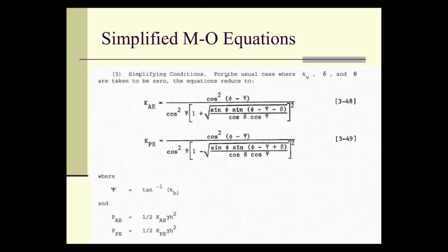Okay, if we get rid of KV, which is common, we ignore the vertical case, which is not always entirely relevant. Earthquake waves have both a horizontal and vertical component to them, and that's where we get into transverse waves and all this good stuff. For lateral earth pressures, KV is not entirely of interest to us, so frequently we drop that.